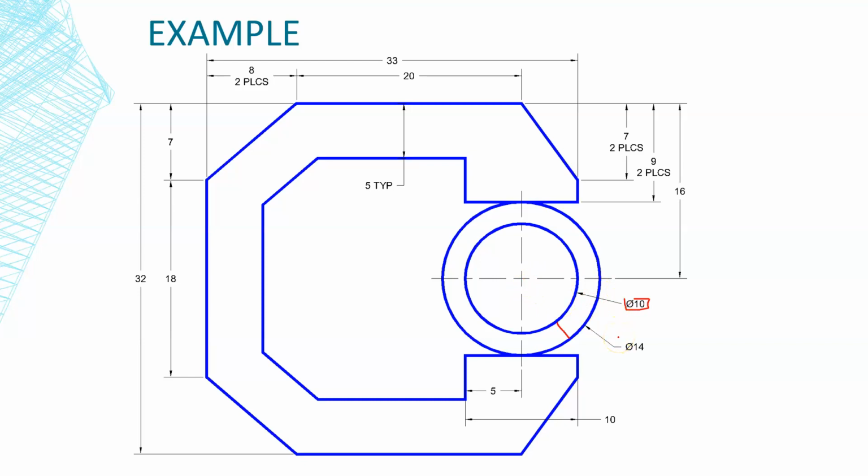But if you want to understand a couple more things about this, this distance, if we subtract the 14 minus the 10, that gives us 4. Now remember that we have two sides of this. What I mean by that is that the number that I have subtracted between these two, I have to divide it. So 14 minus 10 is 4, and then we're going to divide that number by 2, which makes it 2. So my offset value between these two should be 2, and that'll give me my correct diameter of my circle.